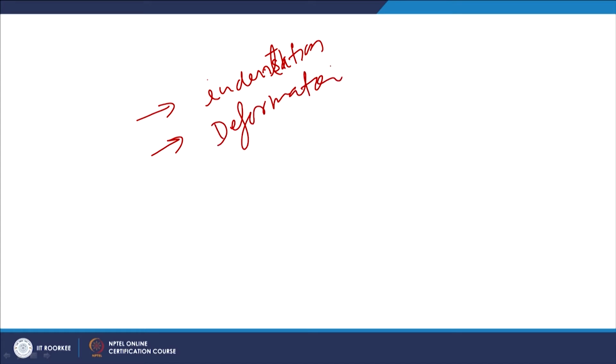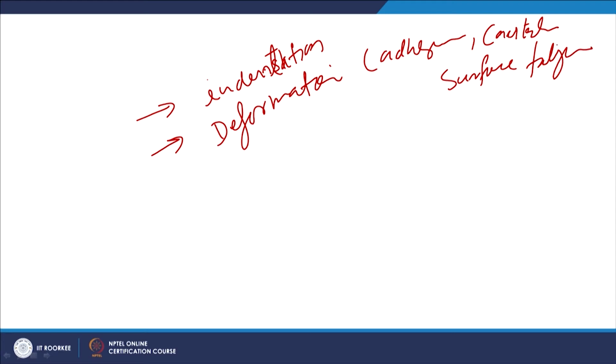Why is hardness important? Because it resists the indentation, this is one. It resists the surface layer deformation. This is especially important under adhesive wear conditions, cavitation conditions and surface fatigue conditions. Too high surface layer deformation will lead to increased metallic intimacy, and since the indentation is affected, it will affect the scratching tendency and metal cutting tendency.